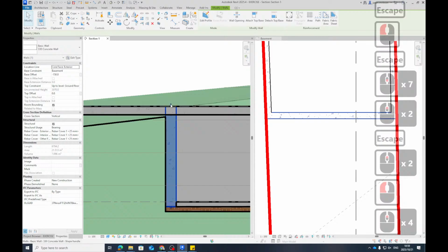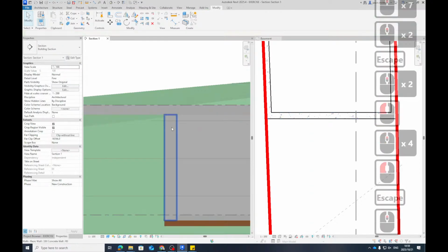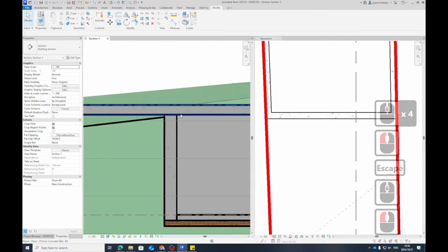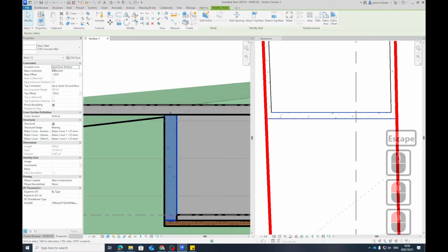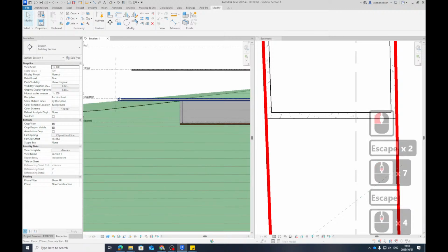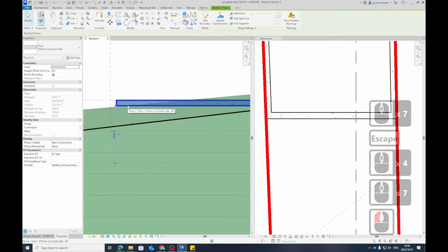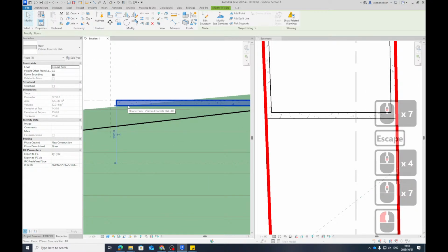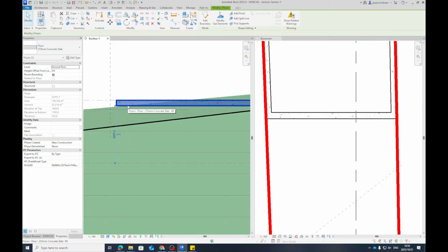Now this wall, you can drag it to the underside because technically it will stop beneath the slab. So remember, this wall will go from basement to ground floor, but minus 255. So whatever the slab thickness was, minus that. Your floor slabs always start from the level down. Everything else works up. It's just the way ArchiCAD works, you can switch bottom or above.